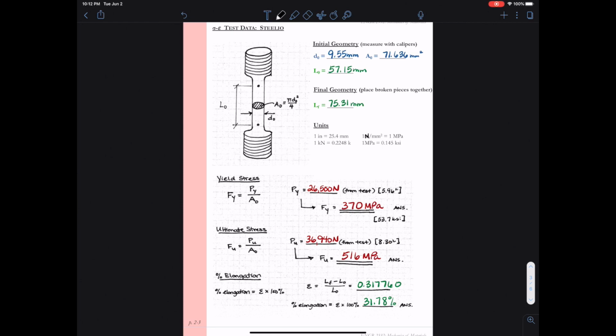So the steel can hold 53,700 pounds for every square inch of material it has. And that's just to the yield stress. Then when we look at the ultimate stress, it can go up to 74,800 pounds per square inch or 74.8 KSI. This is a typical value for a steel that we would build buildings with or fabricate parts with.